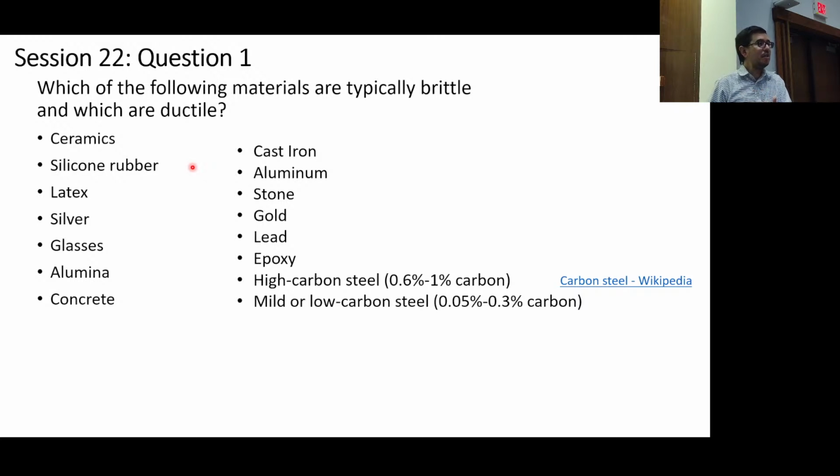It's transparent. It's a rubbery material. It can actually take reasonably high temperatures for a polymer, 200, 300 degrees Celsius. And what's cool about it is you can get it in two parts. That's typical for thermosets, and you mix them together, and then you can pour it into whatever you like, and it has a very low surface energy, and it will essentially wick and get into every single crack as possible. Okay, so this material is used for micro and nano replication, so it can replicate features in a surface.